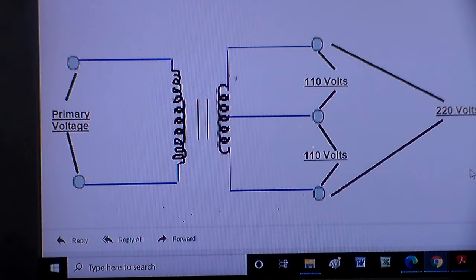Yeah, one of the things I did want to add, in your house you'll have all different types of plugs. Like I said, and I know I show the 110 volt plug, but you can still have some 110s without the ground. They just have the two slots. Some aren't polarized at all, those are the very old ones, the ones you'd want to get rid of and replace, as an electrician.